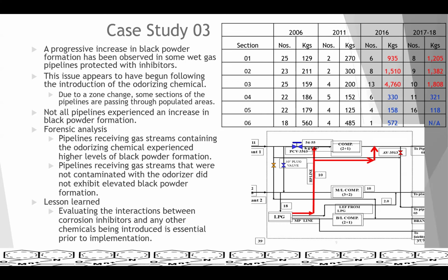To give you just an idea how important that is, I think the surface area, if we talk about iron sulfide, one of the iron sulfides, pyrite, I think 1 gram of pyrite provides 5 square meters of surface area, if I remember right, or something around there, just to show you how much surface area is available to absorb the corrosion inhibitor. So most of the corrosion inhibitor will go to it rather than to the steel pipe. It's really a very important point to make for this case study. Thanks, Motion. Really appreciate it.